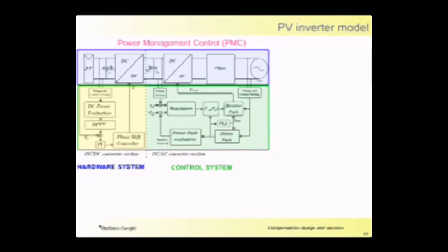As regards the control of the DC-AC converter, it is designed in order to transfer to the grid the power of the panel according to the European standard. In particular, the modulation voltage is regulated in order to transfer zero reactive power to the grid and to maintain the bus voltage at a reference value.